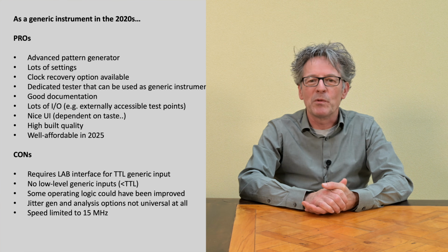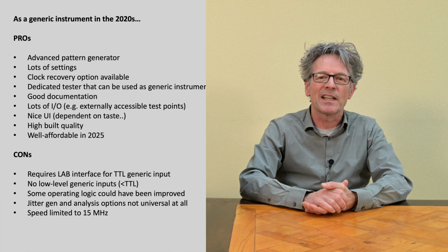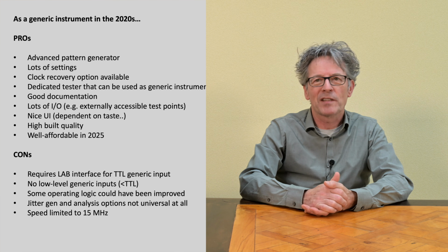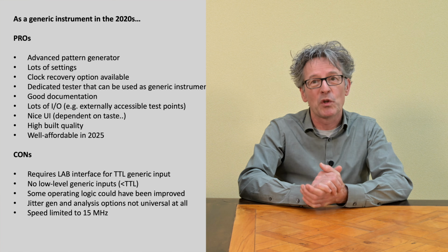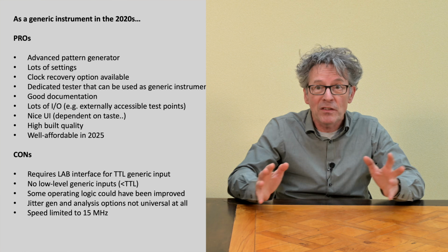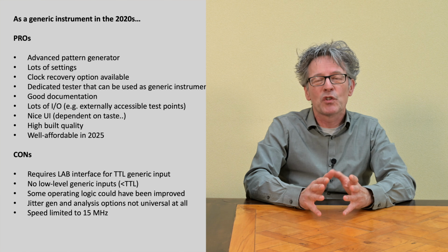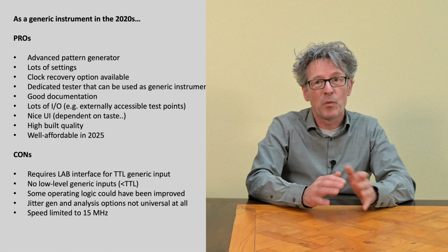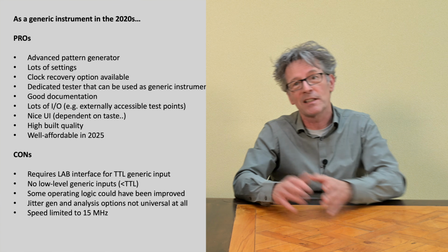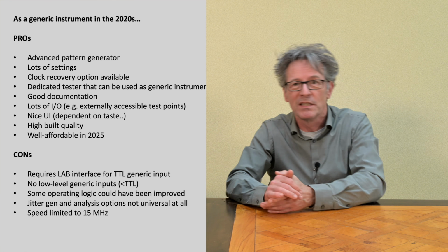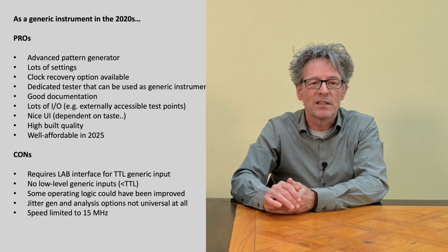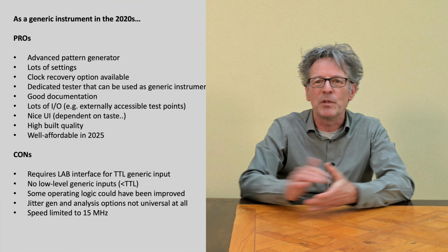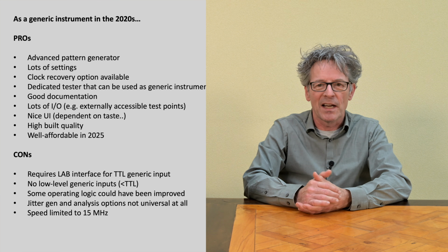Another minus point I would say, yeah, there is a jitter generator and analysis, but these options are not that interesting anymore, I think, for generic use, because they're very limited. I mean, they're advanced, they got a lot of settings there, but they're limited to one single frequency only. So there's one complete set of boards for 1.5 megahertz for the T1 standard, and one specific single board in this case for the E1 2 megahertz standard, but it hardly can be used in any other sense than that.